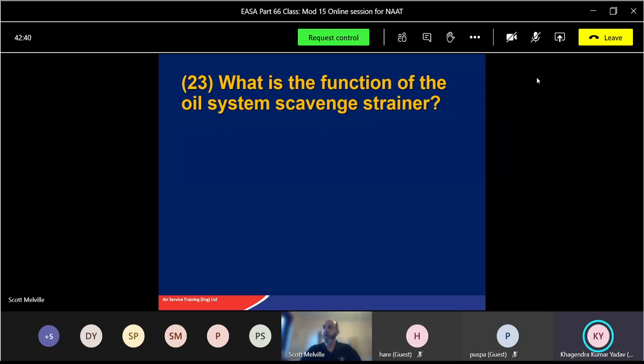Yeah, that's right. What's the function of the oil system scavenge strainer? So what's the purpose of that one? We've got the low pressure filter, we've got the high pressure filter, we've got last chance filters, and we've also got an oil scavenge filter.